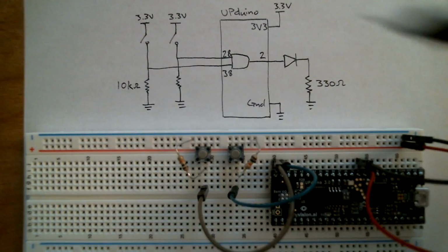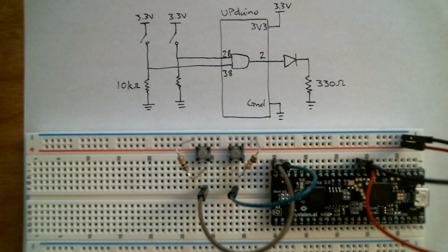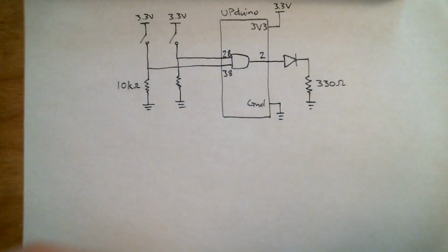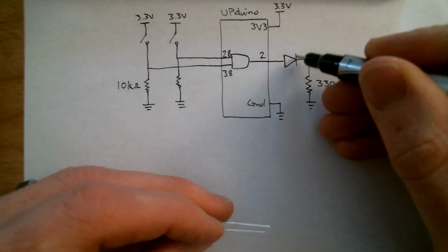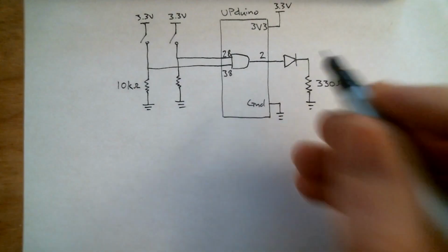The switches are just making or breaking an electrical connection, so it doesn't matter which way they go. Resistors likewise operate the same way, regardless of which direction they are. But LEDs are different. You'll notice in the schematic, the way we've drawn it, there's this triangle and then a flat edge. That's the direction that current has to flow.